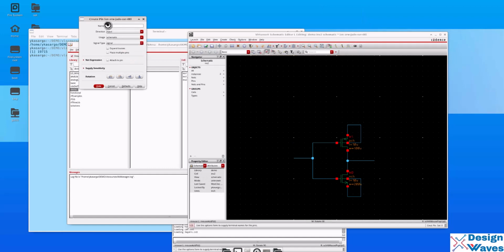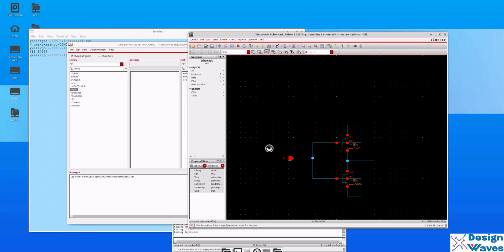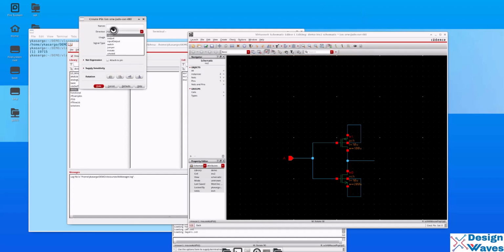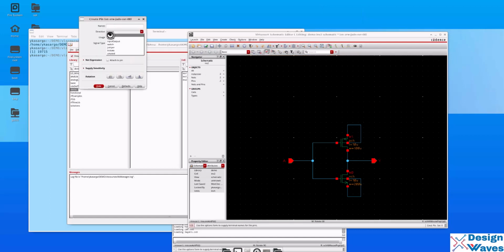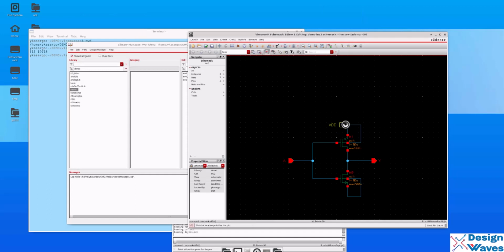Okay. So then go to this. Make an input terminal as A. Then connect to another one. Put this Y. Yeah, and Y is done. Make it symmetrical, which is most important. It will look nice and easy to understand. Then I'll put two input terminals. One is VDD, another one is VSS for the power supply of this MOS.